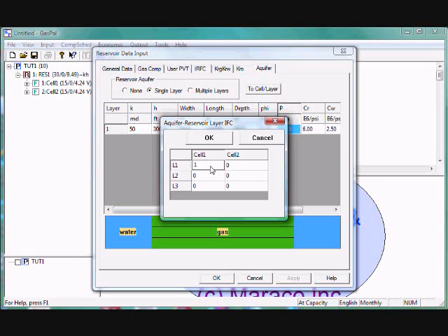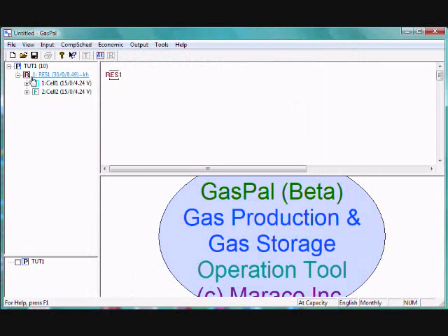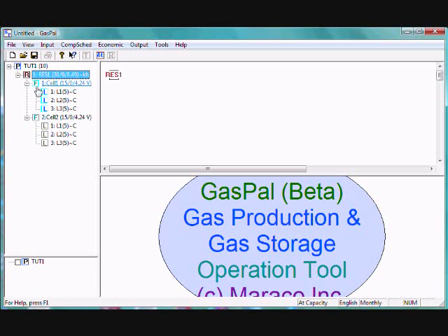We will connect the aquifer to all layers in cell 1 of our reservoir. We'll start by giving the strength of the connectivity between the reservoir and the cell a value of 0.5. As you can see, now cell 1 of the reservoir has a light blue frame showing that there is an aquifer connected to that cell and each of the layers in that cell.